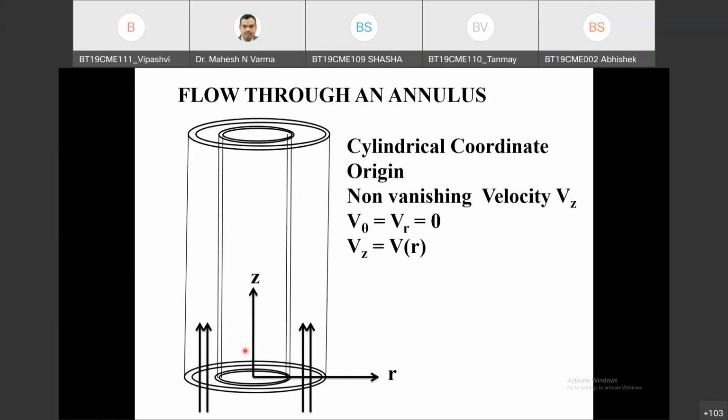Why are you taking the total length? Why is differential thickness taken in R direction? Because the velocity is a function of R. Very good. And velocity is not a function of Z. My properties are not changing in Z direction, so total Z is taken. How about theta? What are the boundaries of theta? Theta will vary from 0 to 360. So the differential shell will be exactly similar to what we did in the previous problem.